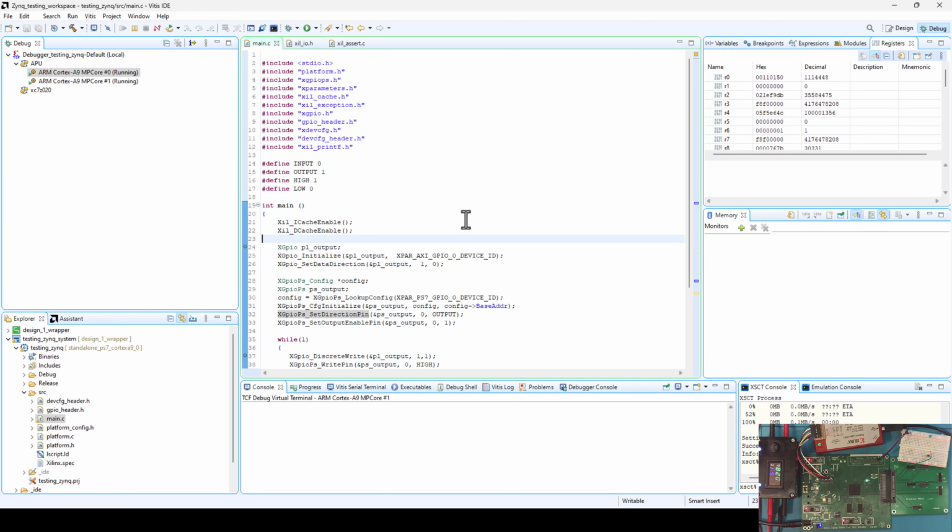And maybe one other side note, when I get to the Ethernet part, that circuit is actually going to provide me a 125 megahertz clock back into my programmable logic. So in the last video, I used a little CAN oscillator up here to provide an oscillator for the programmable logic. But once I get the Ethernet circuit in, it is providing 125 megahertz into my programmable logic. So I'll have oscillators both on the processing system and the programmable logic, and should have some flexibility there.